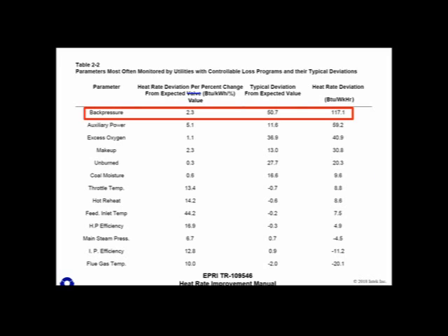Now I do have to acknowledge that the industry has put a higher priority on reliability when compared to efficiency. And all of these slides that I've shown have addressed efficiency. The way I choose to address this higher priority on reliability is this: higher condenser pressure is an early indicator for impending failure. There are few systems that are like that. So number one, they're valuable to monitor and closely make efforts to continuously maintain, and two, prevent unforeseen events from taking a unit offline.